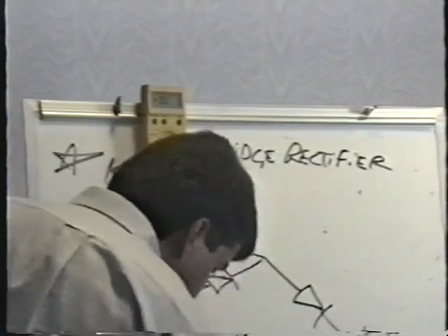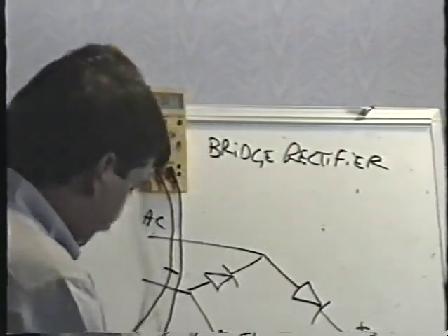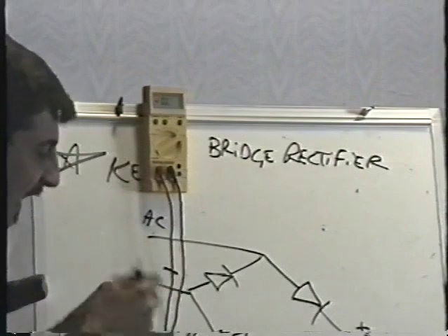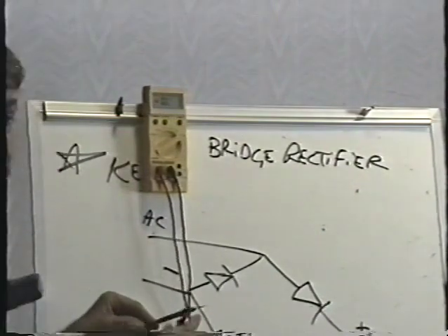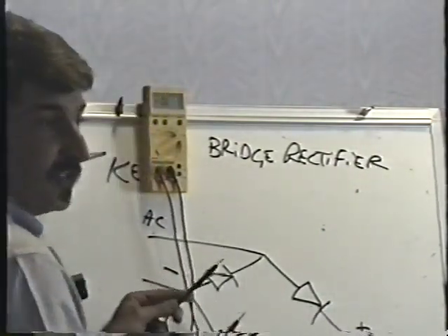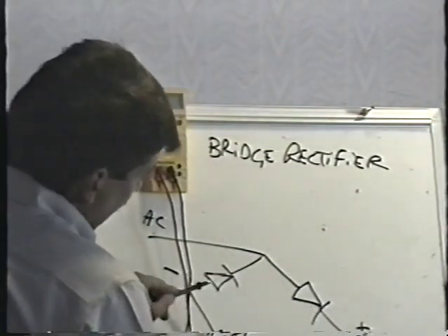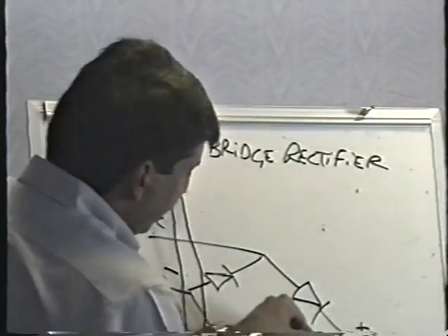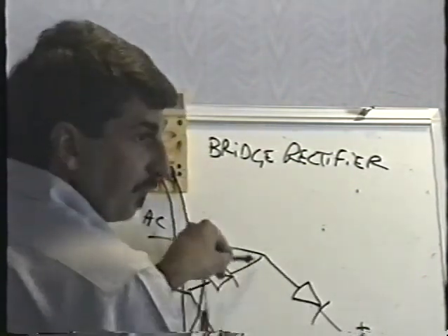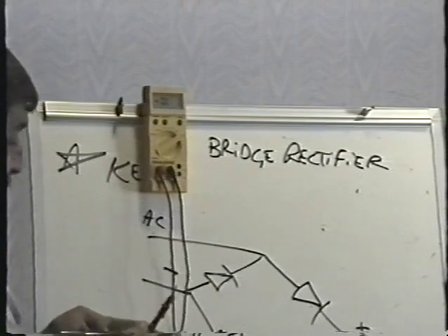Let me check what I believe to be a good one here. And all I'm doing here is I'm checking each. Hang on, you guys, don't do it. Just watch me for a sec, okay? Just to keep it quiet in here. What I'm going to do is check each of the 4 diodes. If any one's bad, we'll know it in a hurry.